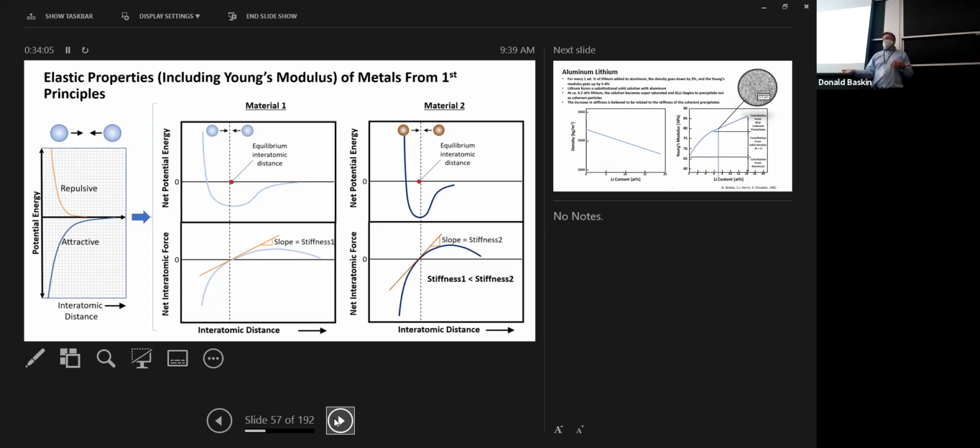If it were the other way around, it would be easy to say, okay, if you meet your stiffness requirements but not your strength requirements, then it's very easy to say, well, let's just substitute a higher strength steel, or let's heat treat it differently. Let's use our computational materials engineering to design a steel that's stronger so that it can meet our strength requirements, because we've already met our stiffness requirements. But oftentimes in a real design, it really ends up being stiffness driven.